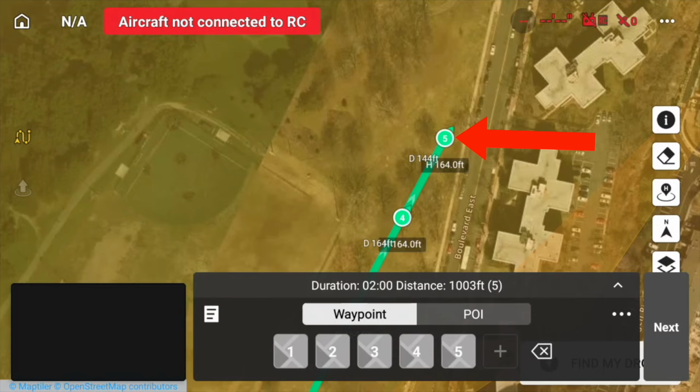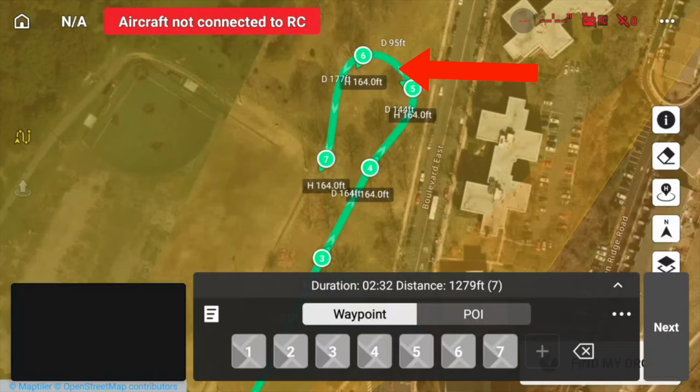By extending your waypoint slightly beyond the boundary, you'll ensure that the turning loop doesn't interfere with your next flight line, which needs to run parallel to the previous one. This approach helps maintain perfectly aligned passes and consistent spacing between flight lines, resulting in clean, professional mapping patterns and accurate image overlap.